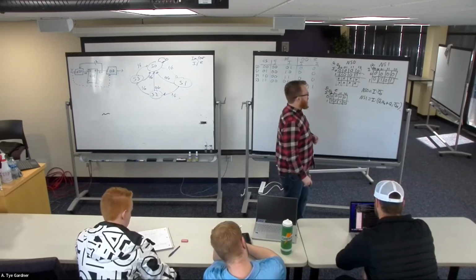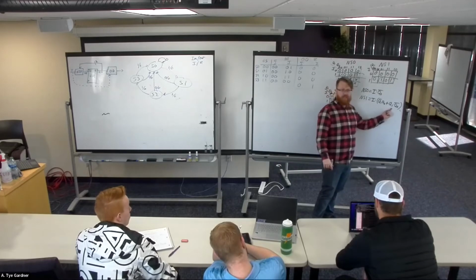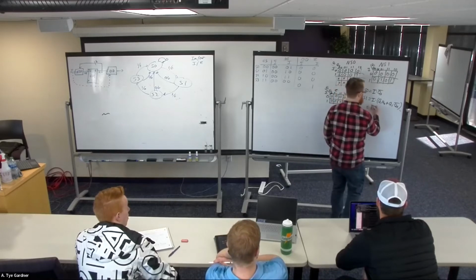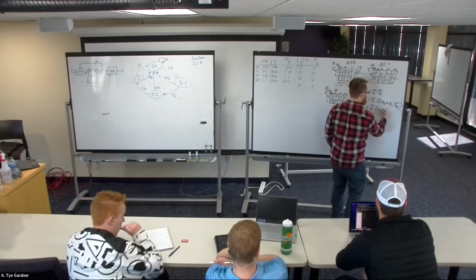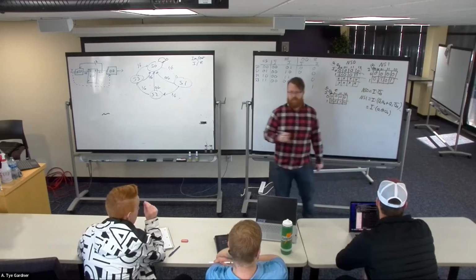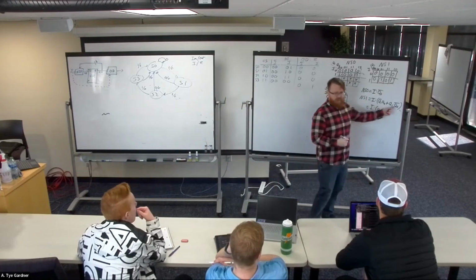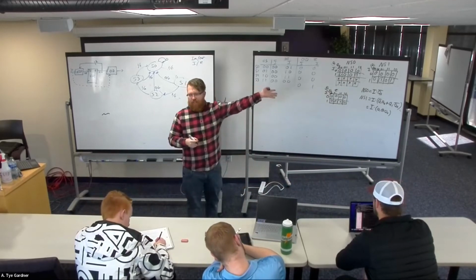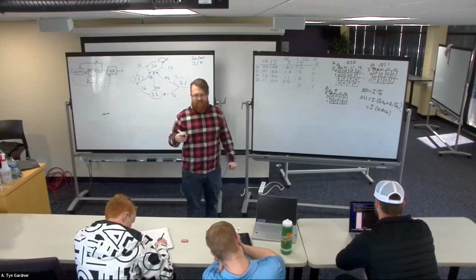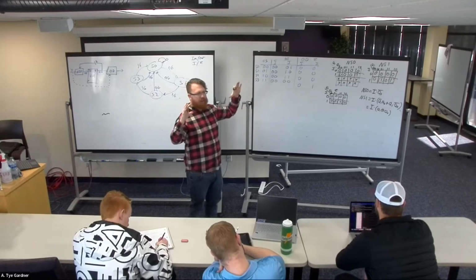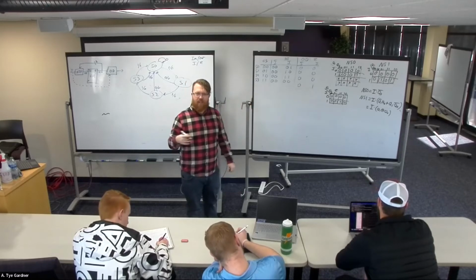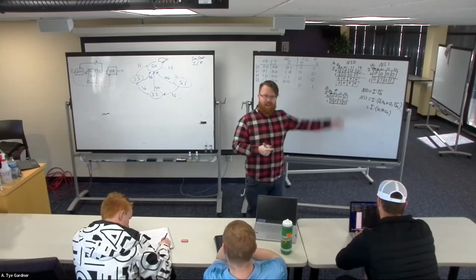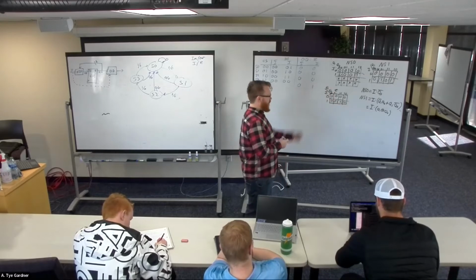And the reason I did that is because I could recognize, does anyone recognize what this is? It's XOR. Right, if it's 0, 0 or 1, 1, it's not true. This is an XOR. Which, if we're trying to build this out of universal gates, is not really beneficial, but if I'm writing this in VHDL, it's easier for me to write I and Q1 XOR Q0 than it is to write the rest of it, right? I just simplified my VHDL writing. The VHDL will then actually translate it into the universal gates for me when I synthesize it. So I simplified what's the easiest for me to type in VHDL. VHDL will turn it into the best circuit for me.